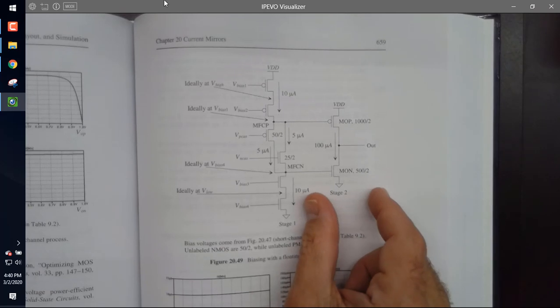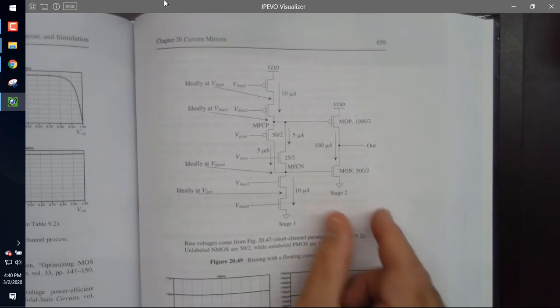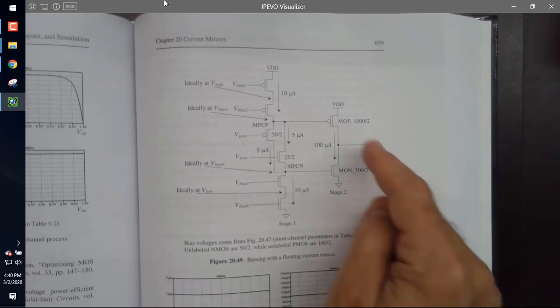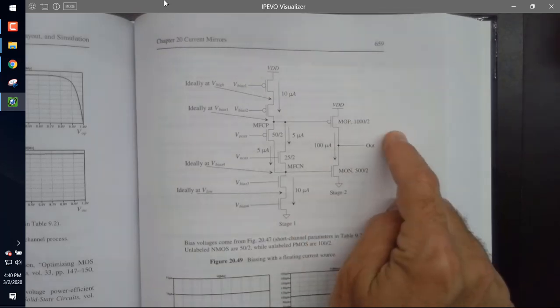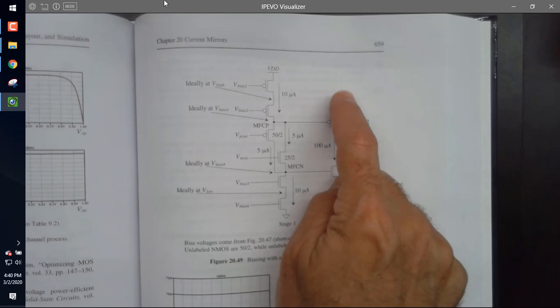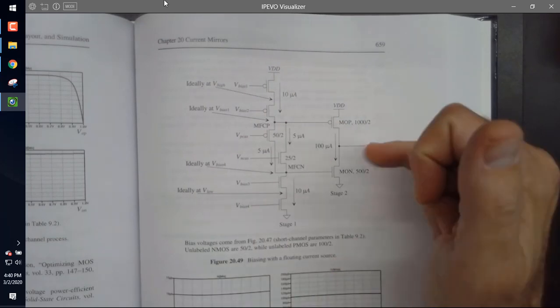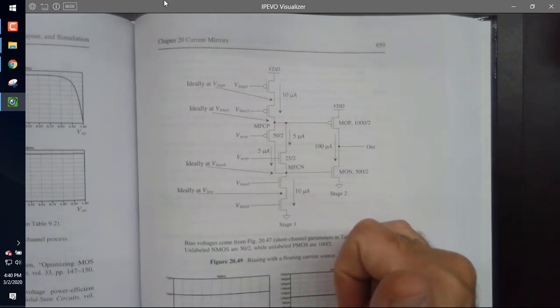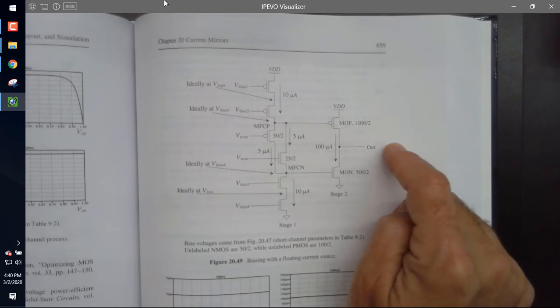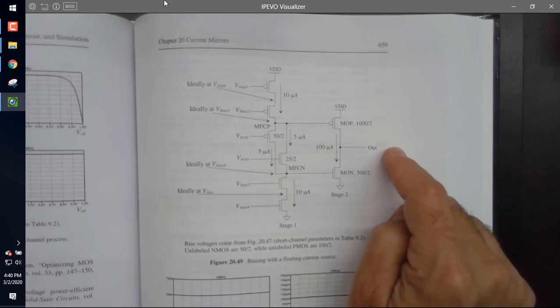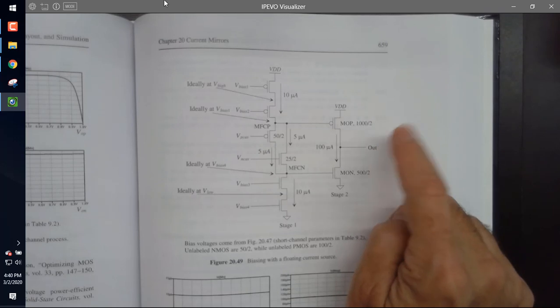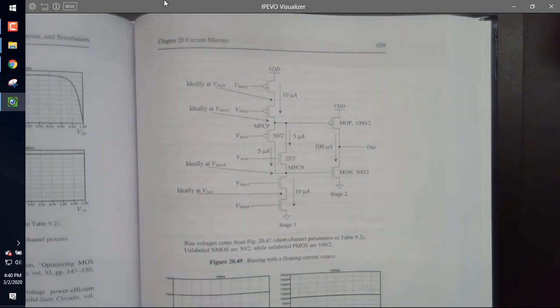In analog talk, this is called a push-pull amplifier, because you can push a current or pull a current. So when you turn PMOS on, it can push a current out, or you can pull a current back, okay? So if I ask you now, knowing everything needs to stay in saturation, what is the voltage swing on the output node?